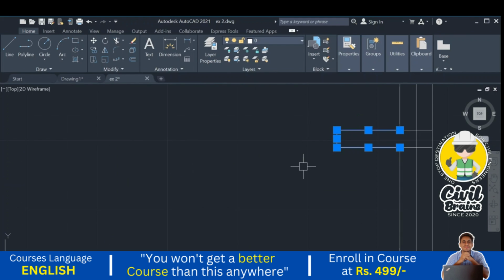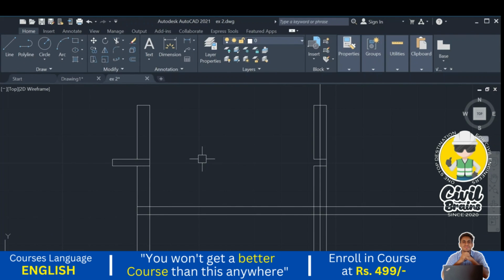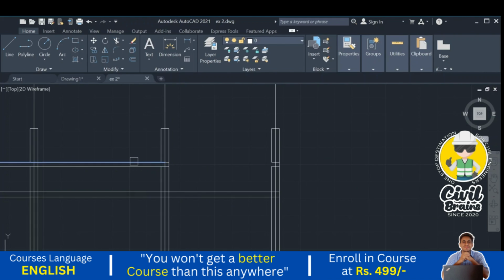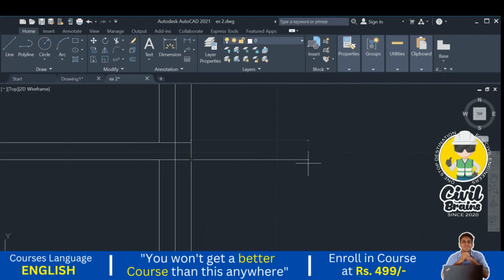Next one is slab. Or else I just use extend, EX, extend. Then projection, how much? 0.45, press enter, 0.125, press enter, and 0.45, enter, enter.